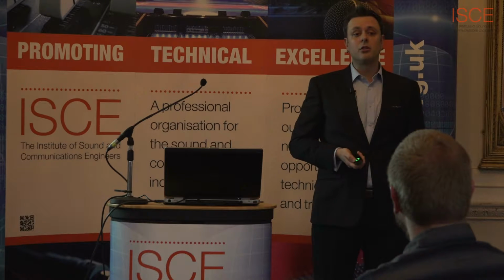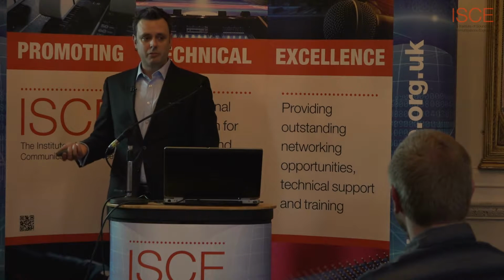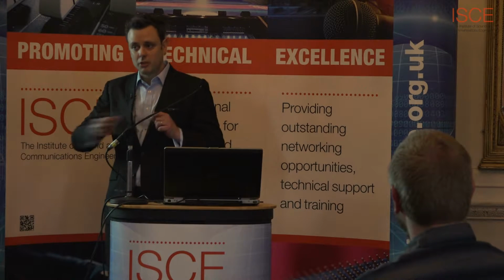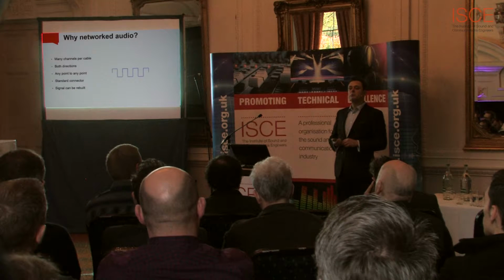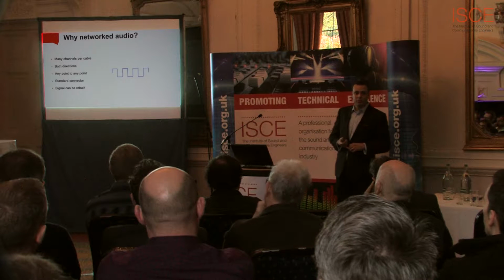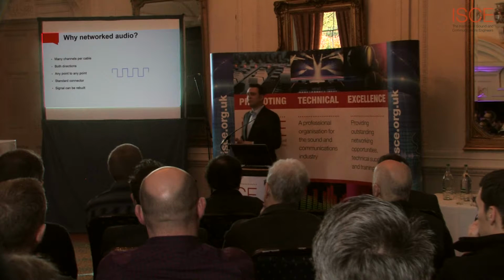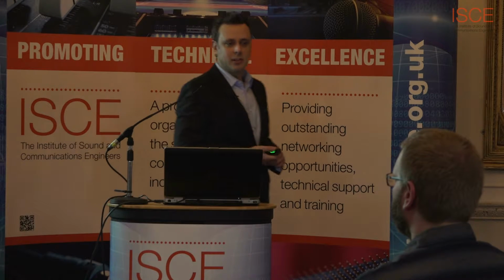And the other common improvement of network audio over analog is that analog is subject to degradation. As soon as you start running it a few meters, you are going to have signal degradation for a number of different reasons. Now, network audio suffers from degradation as well, because it's an electrical signal going down a cable, or a bit of light going down some glass. But because it's digital, it can be rebuilt without adding any more noise. Rebuilding analog audio without adding noise is not that simple. Doing it digitally is very, very simple indeed. So those are the very basic reasons why network audio tends to become an interesting proposition in some cases.